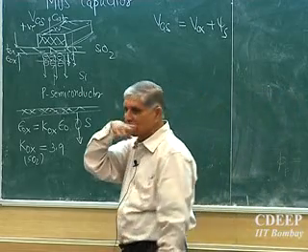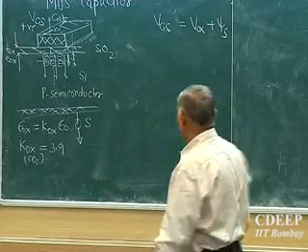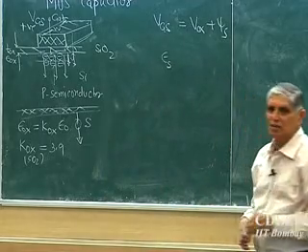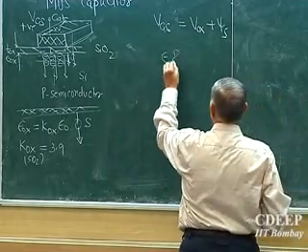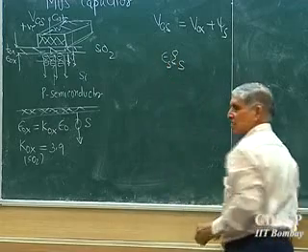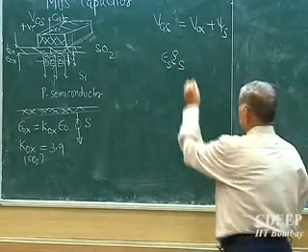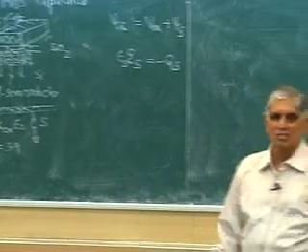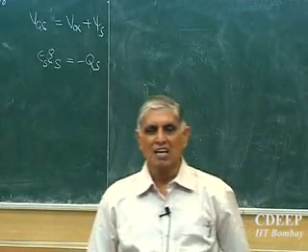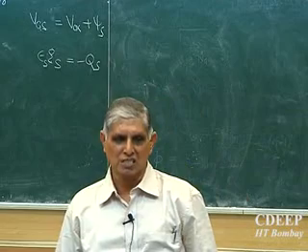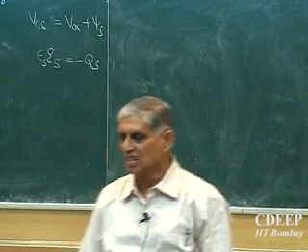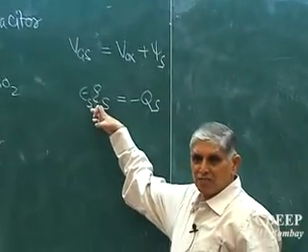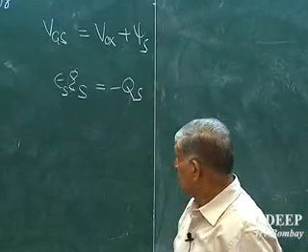He said, two things I can think of in Gauss's law. One is, if epsilon S is the permittivity of the semiconductor, and let us say the electric field in the semiconductor at the surface is ES, this is equal to minus the semiconductor charge. This is Gauss's law's definition. The semiconductor charge density is equal to epsilon S into ES. ES is the electric field in the semiconductor at the surface. Epsilon S is the permittivity of silicon. That is equal to this.